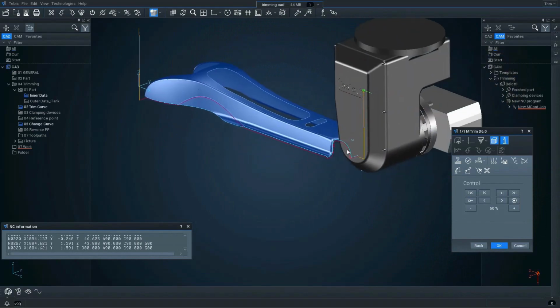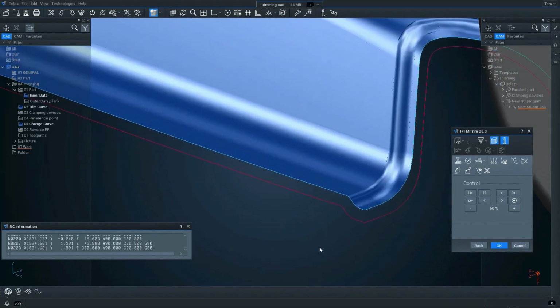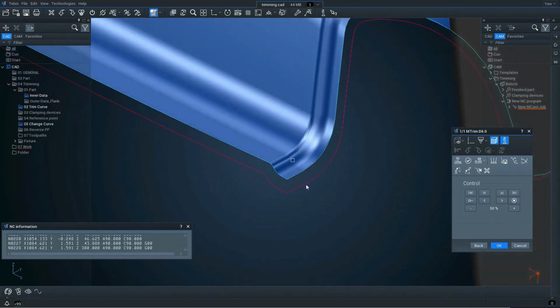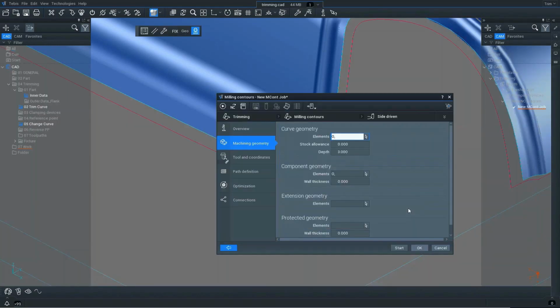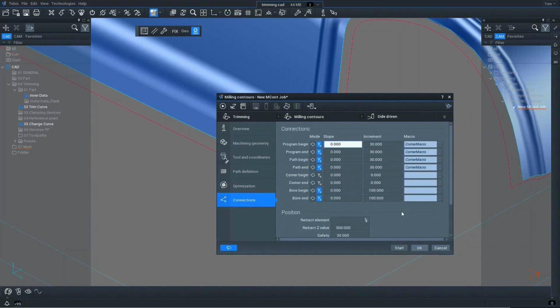One of the problems a lot of trimmers come across, especially with thin sheet plastics, is when we're machining around corners, we can sometimes get some snatching and breakage on these absolute corners, whether that's through a combination of the cutter dynamic or whether it's the clamping. The ideal way to deal with this is to create some relief in the corner. So if we come back to our programming process, we can simply add some corner movement.